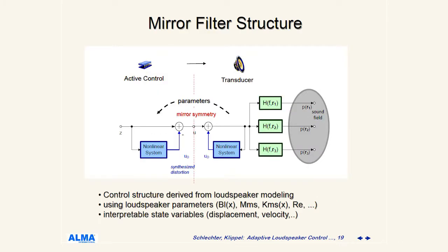How do we do that? We are very lucky with the major distortion mechanisms in loudspeakers. They are very close to the input voltage. They are in a one-dimensional path. Here is the motor, basically, of the loudspeaker, and this is the radiation, the cone vibration and radiation to different points in the sound field. And all the dominant nonlinearities are in the motor, in fact, in the one-dimensional signal domain, so we have good opportunities to reduce the distortion which is generated here.